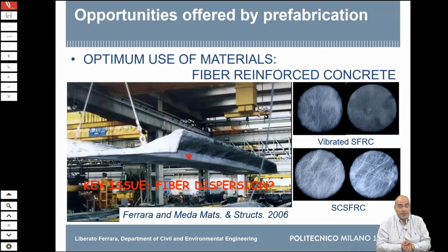And Italy is an earthquake-sensitive country. So this means that you have your cantilever column with a big mass on the top. You have what we call an inverted pendulum, which is, from the earthquake point of view, the worst case that you can design. So reducing the dead load of this element meant that we could have cascade effects also on the design of the wall structure and of the foundations as well.